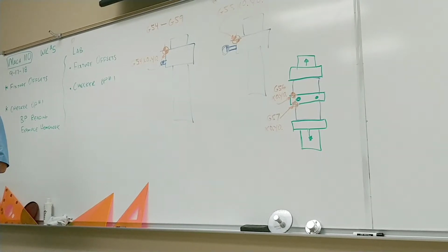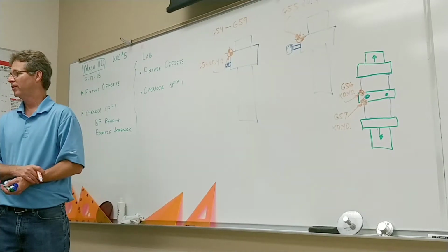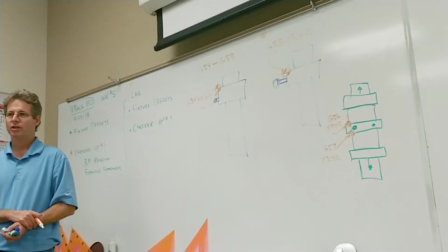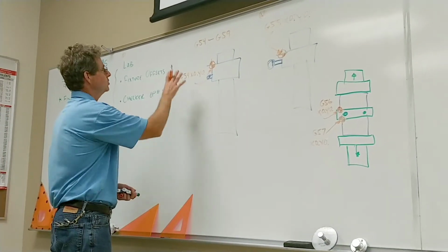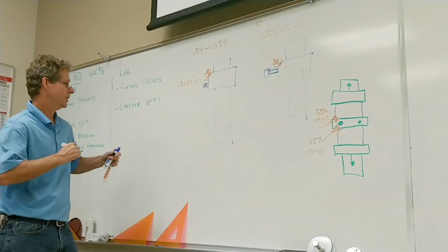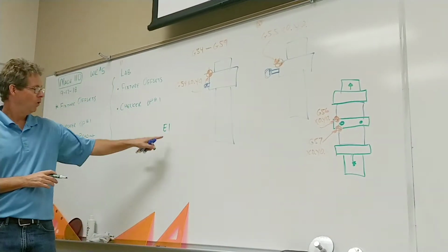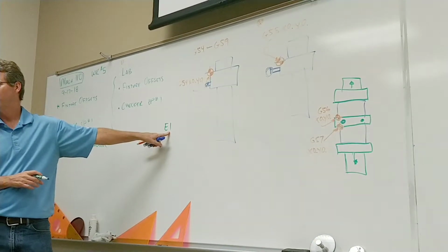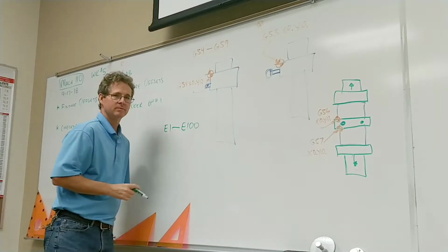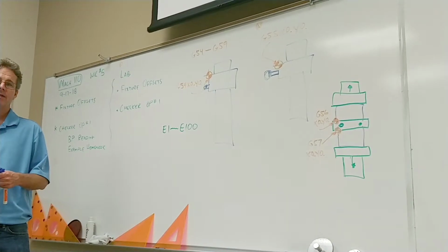their fixture offsets. Okay? That's great, but what if you have more than 6 different parts you run on that machine? Which is pretty much the case of every company, especially ones that do production work. Well, the standard G codes give you the 6, but a lot of machine tool manufacturers have utilized the letter E to do the same thing. So E1 is the same exact thing as G54. But the E on a lot of these machines goes all the way to like E100. Okay? So that's one way you can get additional fixture offsets.